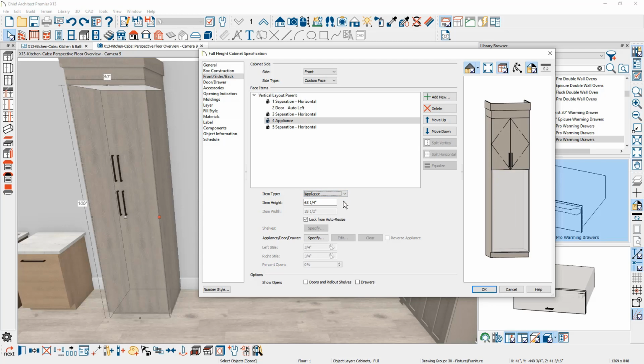And then most of the time what I do is I look at the finish specs for the appliance. There's the cutout and there's the finish. I like to use the finish because appliances will fill the space. And in this case, according to the Decor website, that should be 50 inches and 5/8.